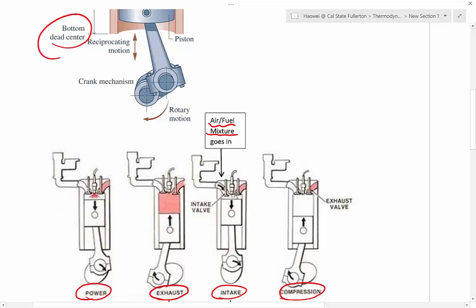That is to say, we assume the hot exhaust will just sit inside the cylinder and do nothing but stay there and lose heat. So it becomes the new cool mixture. So in thermodynamics, we combine exhaust and intake strokes into one single step. That is a heat loss process at constant volume since the piston doesn't move.